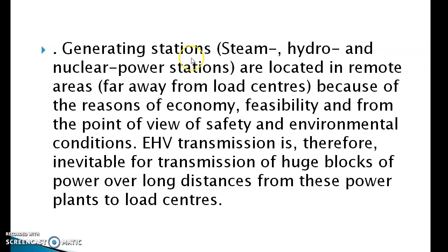The generating stations, particularly steam, hydro and nuclear power stations, are located in remote areas far away from load centers. Because of economy, feasibility, and from the point of view of safety and environmental conditions, EHV transmission is therefore inevitable for transmission of huge blocks of power over long distances from these power plants to the load centers.